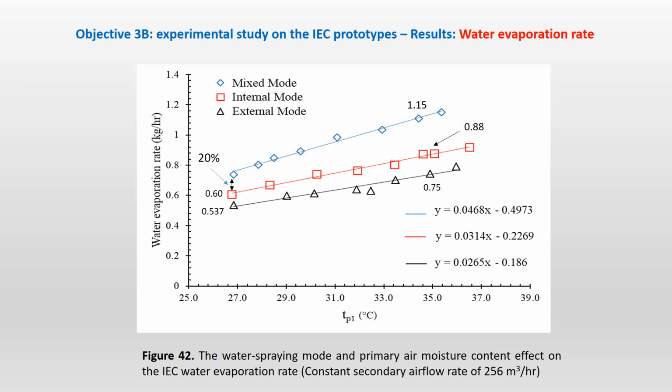Well, let's talk about what's available in real life. The small evaporative cooler, and I checked that myself, is too small. The cooling capacity is too small, and it still sends more humidity to the room, and it's consuming something between 2 to 2.5 liters per hour on hot days. So by having better cooling efficiency and a better cooling rate, with 1.15 with the mix, it's great. Yeah, that sounds good. But actually, in the next study, the one I told you about that we're going to work on together, I'm not going to use any of these sprayers. I have a different method for the water distribution.